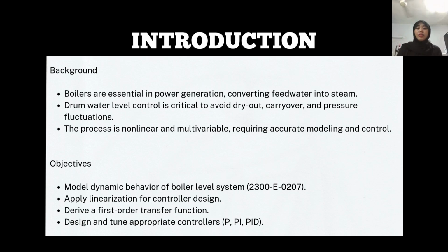First, I'll be presenting on the project background. In modern power plants, boilers play a key role by converting water into steam. Controlling the drum water level is crucial to avoid hazards like boiler dry out or water carryover. This system is nonlinear and complex, requiring proper modeling and control.